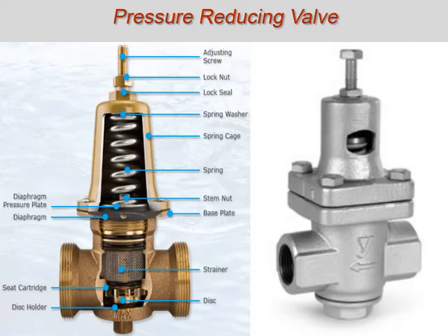Pressure-reducing valves are specially designed valves that automatically reduce downstream fluid pressure to a set pressure, for example 150 psig to 50 psig. This allows for the proper pressure to be applied to each system or component. The desired output pressure of the reducing valve is set by positioning the adjusting screw, which adjusts compression on the interior spring. The adjusting screw forces the adjusting spring to push downward on the controlling diaphragm.